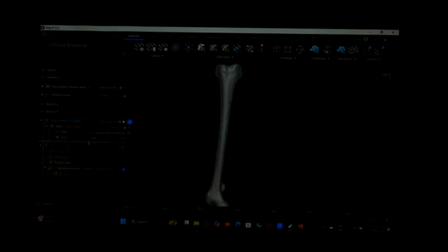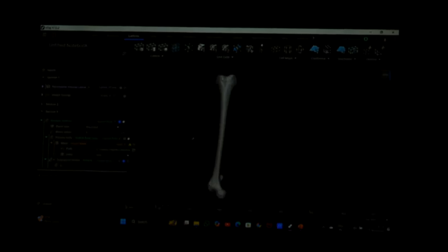Boolean subtract, I am subtracting with respect to planes, the reference planes, right? With respect to reference planes I am taking. So I need to separate this body, I need to extract the middle body. How many cuts should I give to extract the middle body? Two cuts. Here one cut, here one cut, right? So I need two planes. I will press this so I can get the two planes. I can press plane or reference plane. I can use the plane from normal.